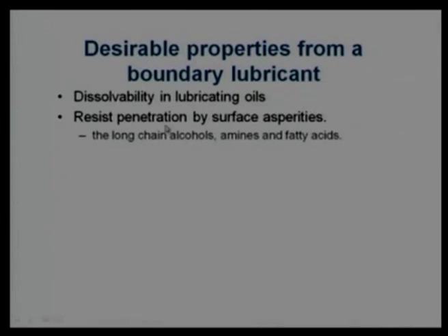And it should be able to resist the penetration of the surface asperities. When one surface's asperities approach the other surface, these asperities should be covered with the lubricant additives, so that they are not coming in direct contact with the surface as far as possible. In that case we will be in the mild region.